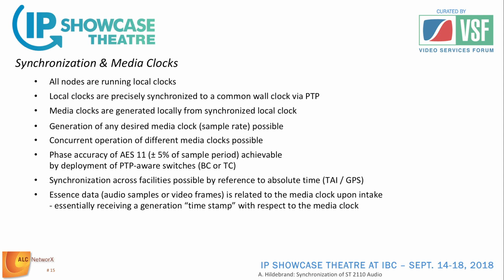Now, once we know when it has been created, the magic trick is, first of all, on the receiver side, we can fix or configure a deterministic or fixed playout delay. Why would we want to have a playout delay? Well, because first of all, samples need to be gathered before they can be put into a packet. 1 millisecond packet time means 48 samples. The sample has already a latency of 1 millisecond at the transmitter side.